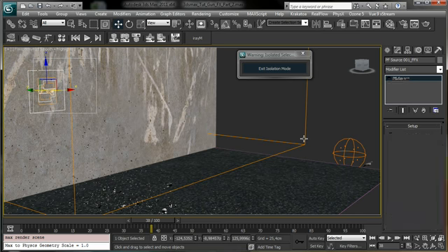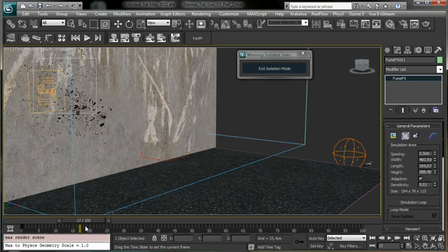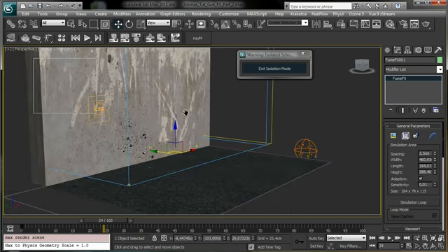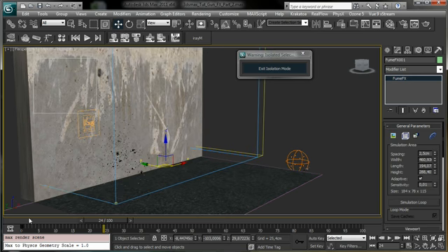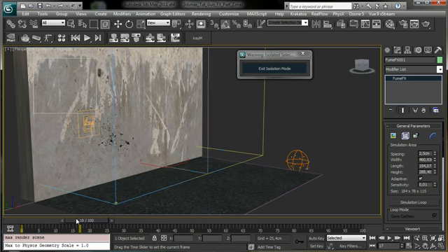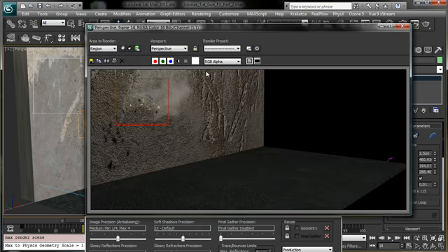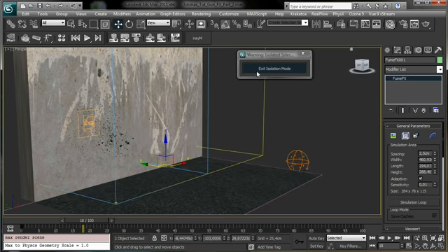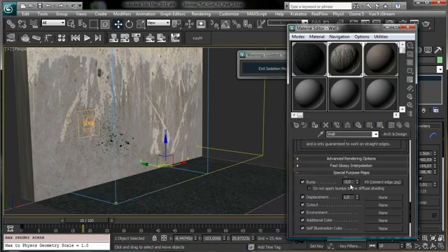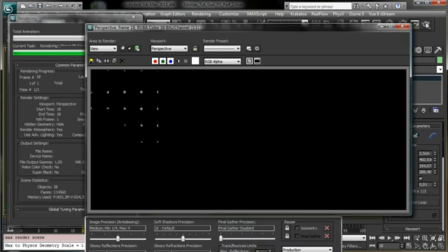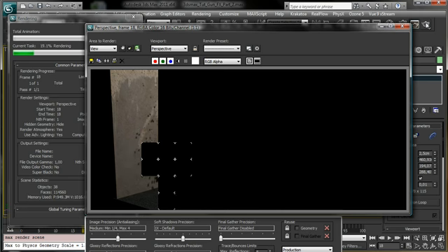We can zoom just a little bit. Okay. Let's see, for example, there, which is the result. And let's go there. And let's say we can render. I'd like just to remove a little bit of bump from the wall to be faster in rendering. So minus 0.5 and render. And let's see what happened. You see it's faster now to be rendered.